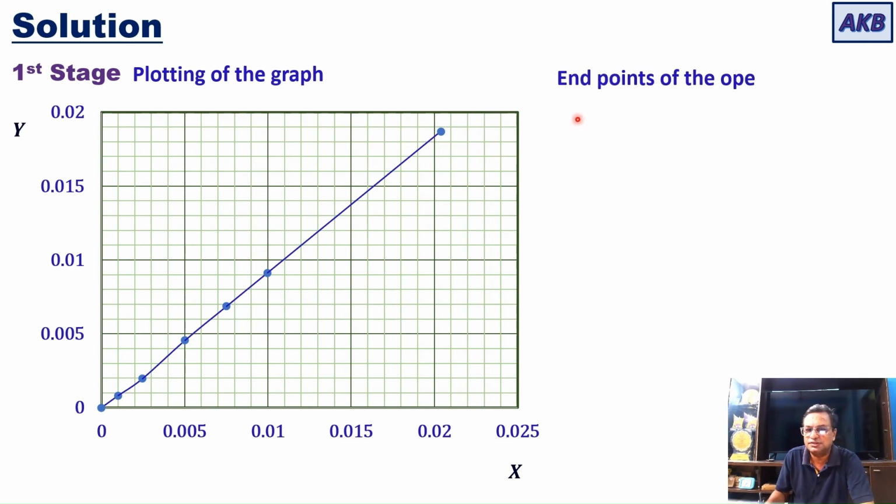Okay, so for the first stage, the operating line for the first stage has endpoints: one endpoint is XF, YS, and the other endpoint is X1, Y1. One endpoint you can locate because XF and YS are known, and we have to find out the coordinates of the other endpoint, that is X1 and Y1. The slope we just got, that is minus 2.12, or the angle measured in clockwise direction is 64.5 degrees.